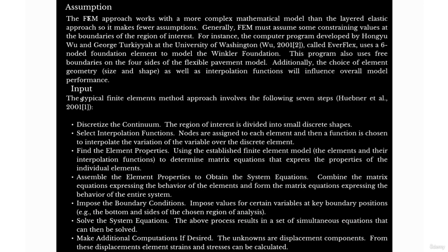So the assumptions. The finite element approach works with a more complex mathematical model than the layered elastic approach, so it makes fewer assumptions, which is true. Generally, the finite element method must assume some constraining values at the boundaries or the regions of interest.